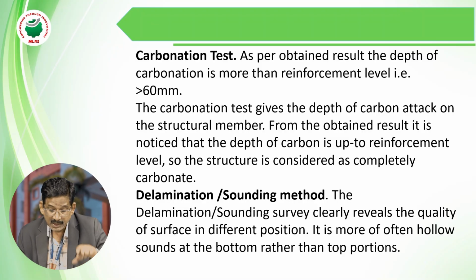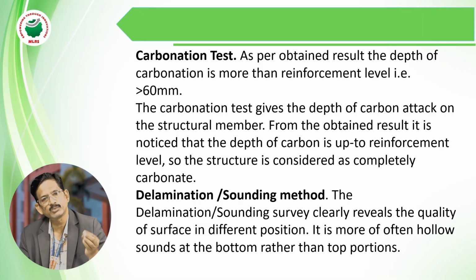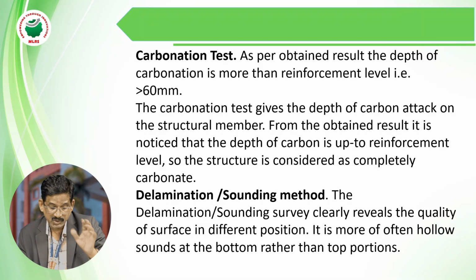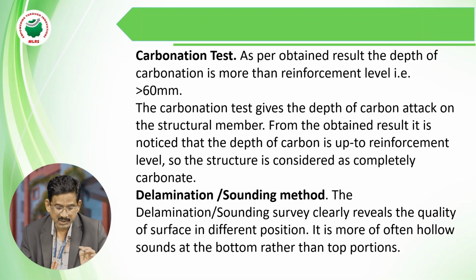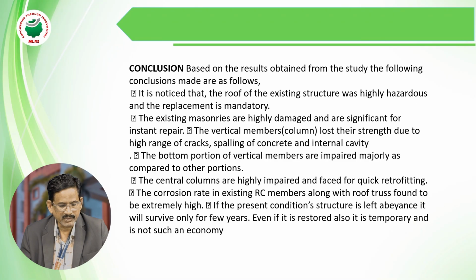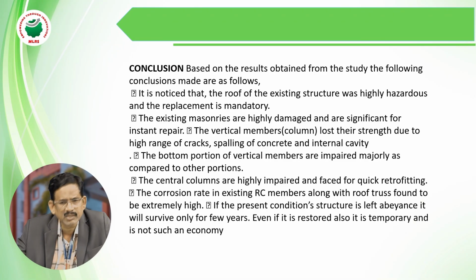From the obtained result, the depth of the carbonation is up to the reinforcement level, so the structure is considered completely carbonated. It is more than 60 mm, so it is a completely carbonated structure. Next, the delamination and sounding method. This also shows yellow sounds at the bottom of the member itself. Next, the conclusion. What is the conclusion for a particular member?